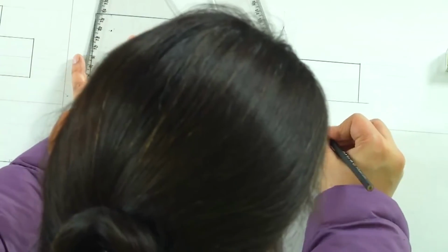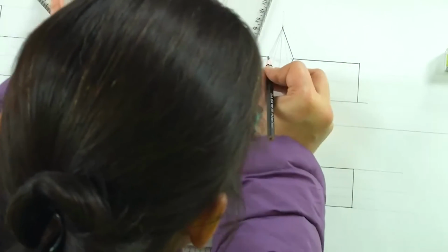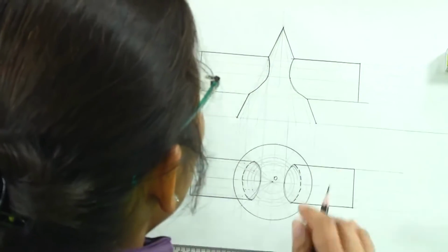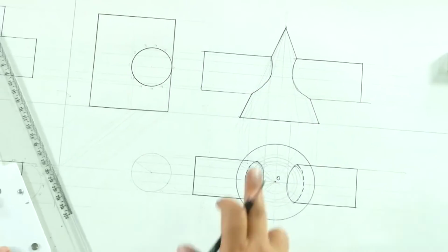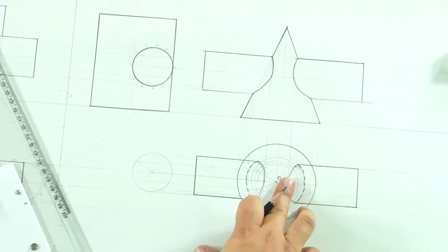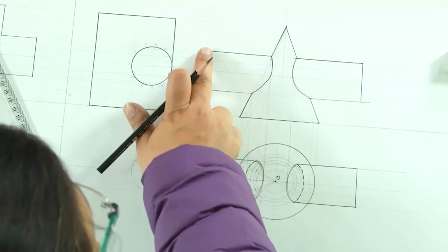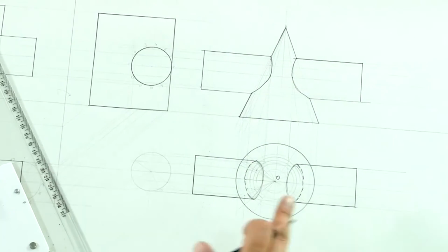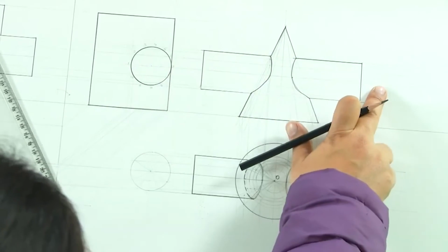And this is how the cone will be intersecting with the cylinder in the elevation, and this is how you will actually be seeing it from the top. If you see it from the side, you will only be seeing a flat circle alongside a cone, or right in the middle of the cone here. So, that is how we will derive the projections of a cone being intersected by a cylinder.